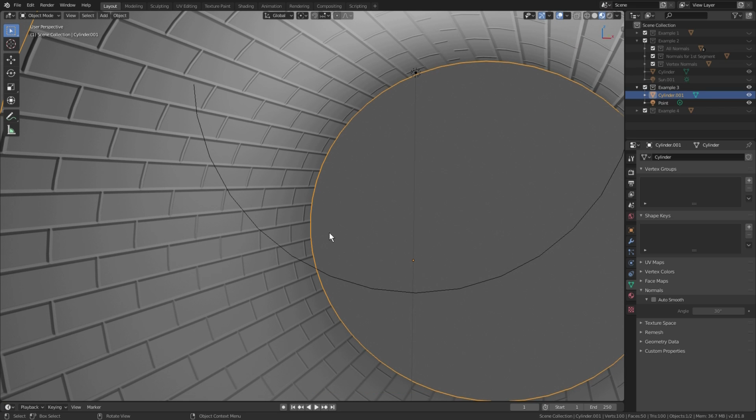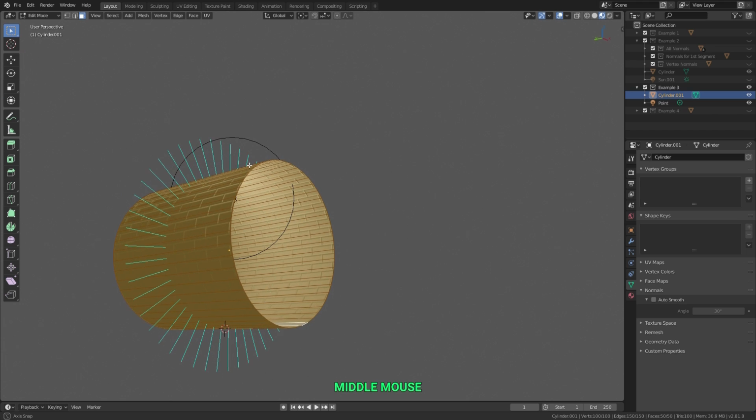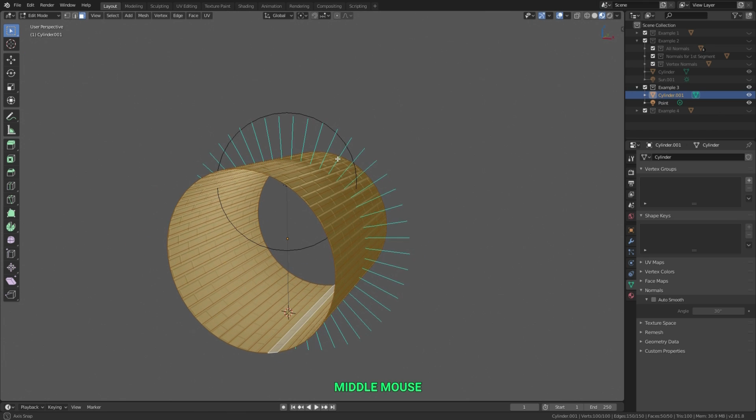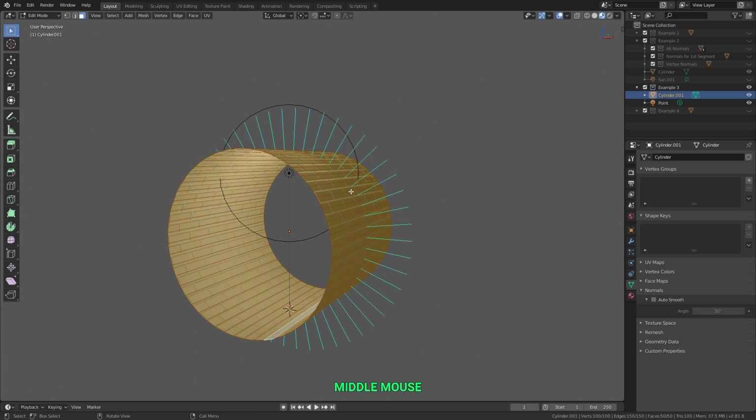And that's one good reason it's important to make sure your normals are facing the direction that's rendered, because they can affect things like normal maps. Above all though, it's most important to make sure your face normals are just consistent in their direction. Because like we saw earlier, we had some faces pointing inward and some facing outward, and we ended up with some serious shading issues. So keep that Shift and N hotkey in mind to recalculate normals. And if you have any shading issues, this is usually a good first step to troubleshooting.